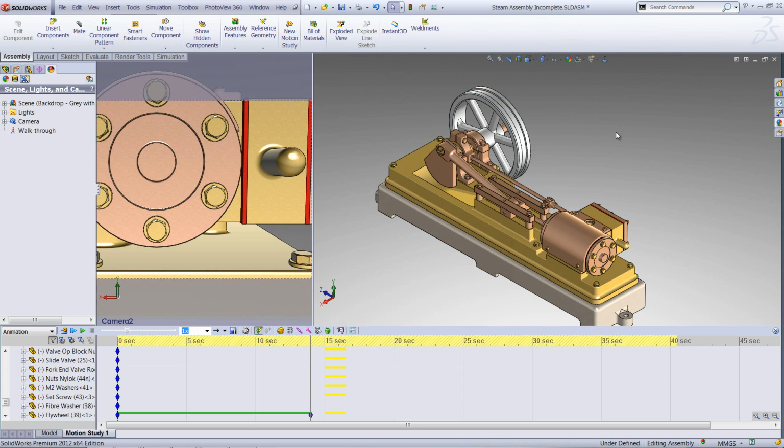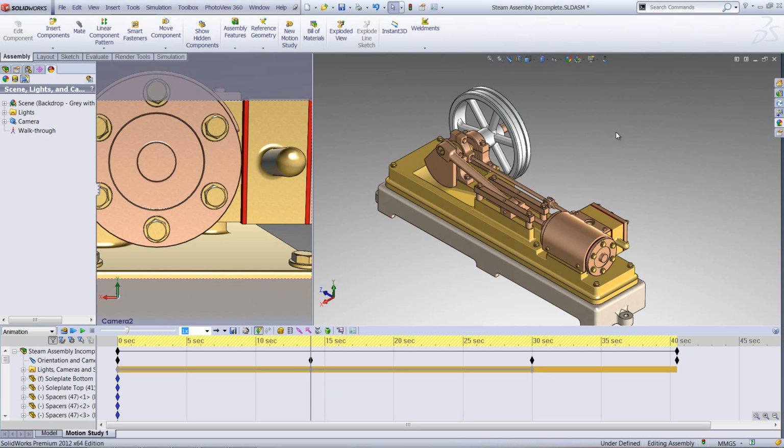Now I could go about the same approach we did with the first assembly, which is to use the position-based animation process. So I could manually move that wheel at different positions to create the mechanical movement. But what we are going to do instead is drive this animation with a motor. So with this motor, we can drive mechanical movement whilst controlling its parameters at key points. So that's what we're going to do secondly. So we're going to go to motor, which is this button here.